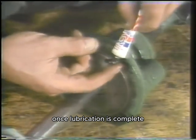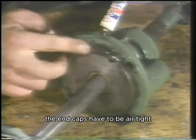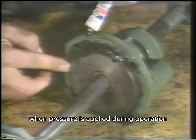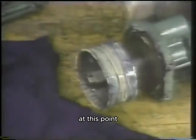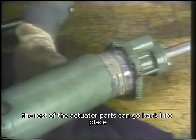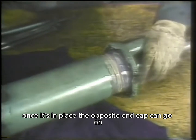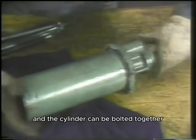Once lubrication is complete, sealant is applied to the end caps. The end caps have to be airtight, so no air leaks out of the cylinder when pressure is applied during operation. At this point, the rest of the actuator parts can go back into place. The cylinder slides on over the piston. Once it's in place, the opposite end cap can go on, and the cylinder can be bolted together.